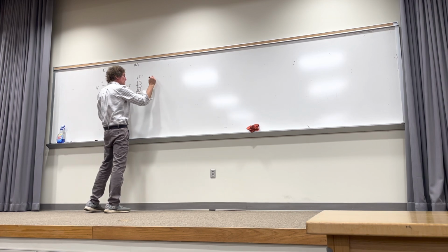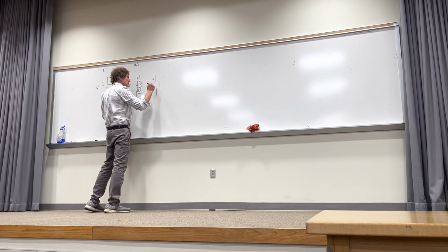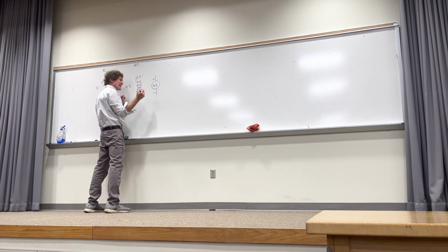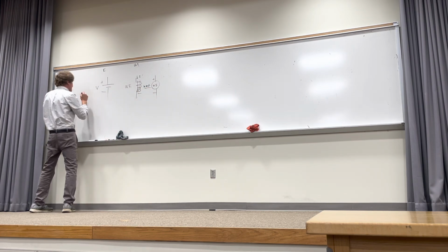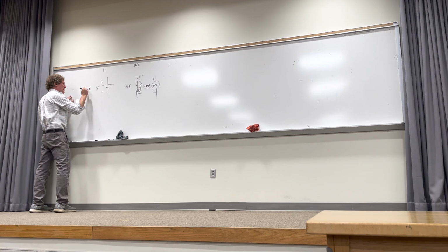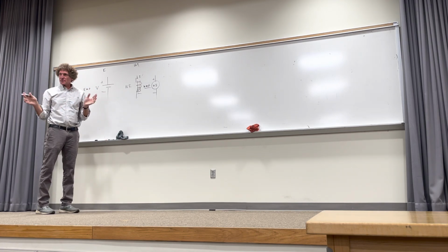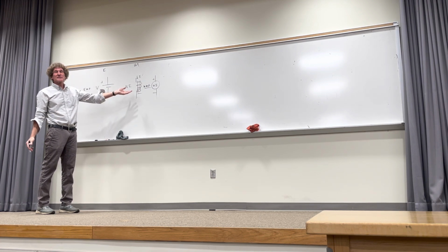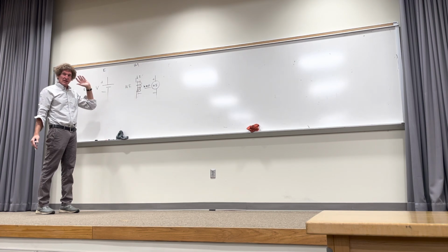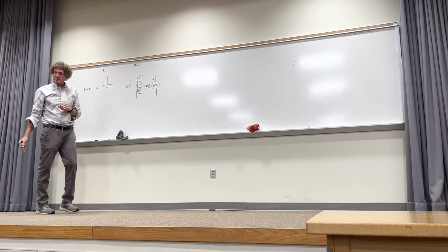The symbol that they use is this, plus or minus, with Ni. This is the magnetic force. It's the number of turns times the current per turn, and this is called a magnetomotive force. Technically, this is the EMF, the electromotive force, and this is the magnetomotive force. Don't worry about this right now, I'll show you how it works. Everybody knows what a voltage source is, right? So think of turns times current as a magnetic force equivalent to the voltage in terms of what it does.